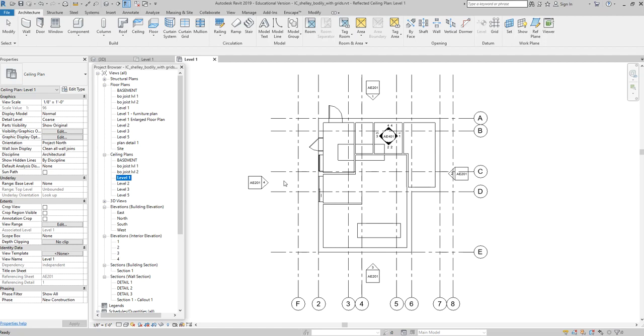stuff, okay? So I will probably adjust our view range in our ceiling plans, and I will likely bring it down just a little bit to like 6'6", so that my view range cuts all the doors and windows and I can still orient myself in the space. Does that make sense? Because I can see the doors and windows, the architectural elements, and then I'll still look up. Okay? I'll talk about it continually, the view range topic, because it's really confusing.